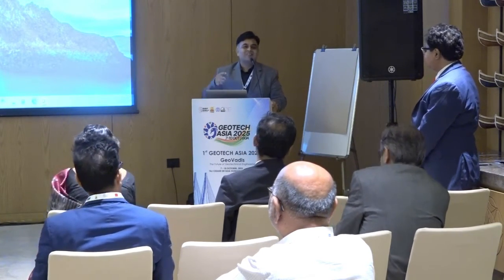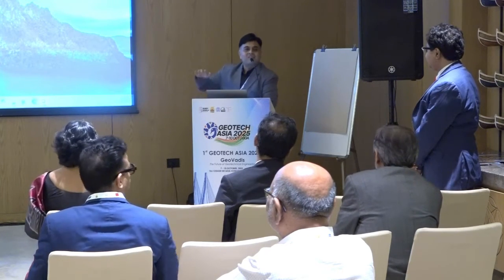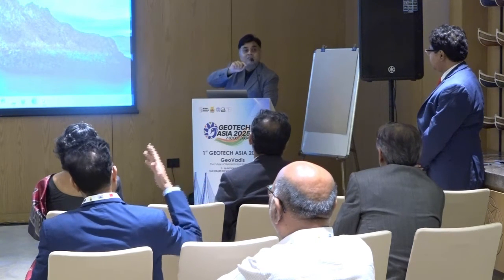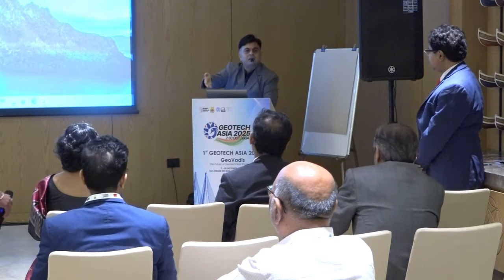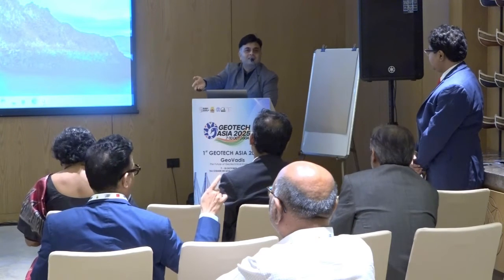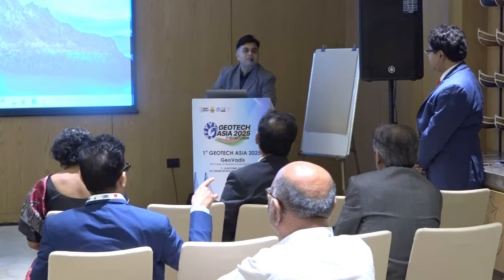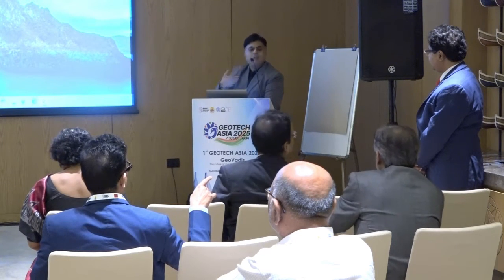No, you are right. Actually, it should be a surface settlement marker. I think actually, I will be going against you. But instead of putting in a deep settlement marker, again I'm going against you, it will be better to just mark a plus sign and measure it by a level. You don't need anything actually if you're doing that. Just do the surveying and take the deformation by leveling. No point in putting that.